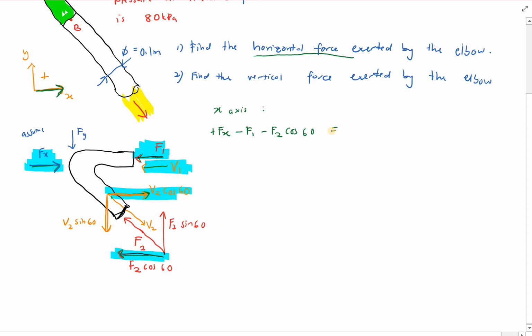and we look at the velocity components. Okay, in which the force is given by rho times V times the AV. Okay, if you have a system, if it's entering a system, then your AV becomes negative. If it's leaving a system, your AV becomes positive.